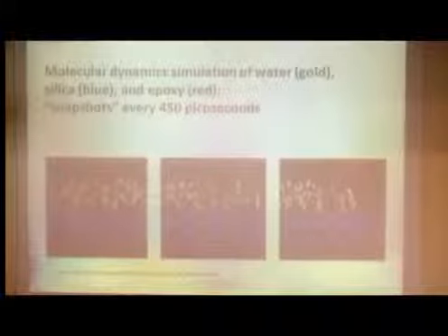And for example, this is a molecular dynamics simulation of water. This is the gold here, the silica in blue, and the epoxy in red. And these are snapshots every 450 picoseconds. And you can see that very quickly this red epoxy comes away from this blue silica, and the water interjects itself in between. So it's very important to be able to functionalise these materials.